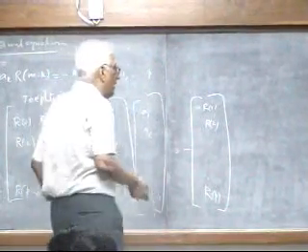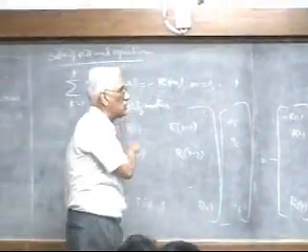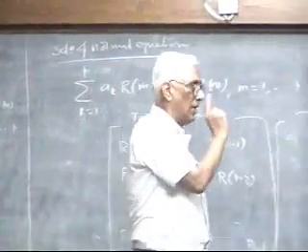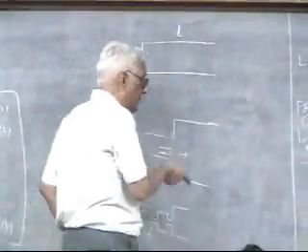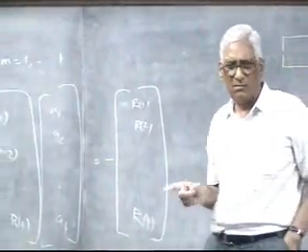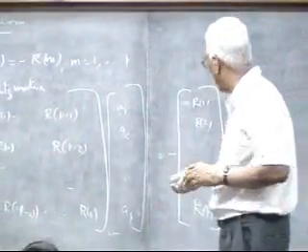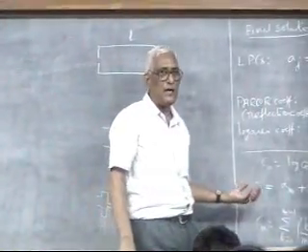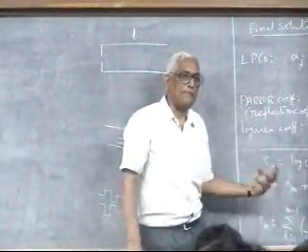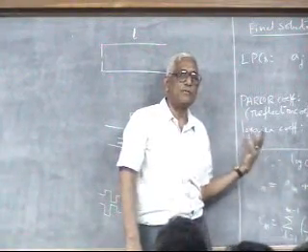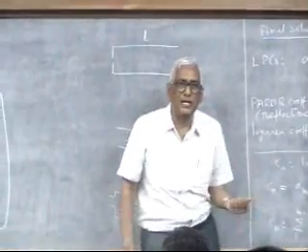So, this is about the solution of these normal equations: reflection coefficients, LPCs first of all, and then the refraction coefficients, and then the area coefficients. Is that all? No, there are many, many more, and I think a few of them I have written here, one more step here. These are what are called the cepstral coefficients. You can also express these linear prediction coefficients in terms of cepstral coefficients. What do I mean by that?